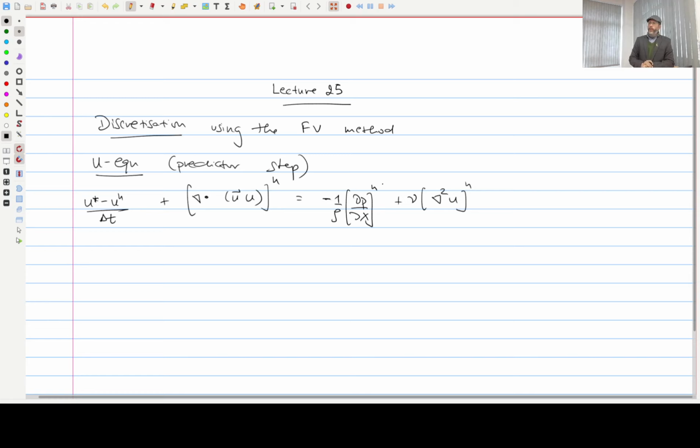When we use the finite volume method, using a conservative form is much more comfortable, because then we can easily integrate it and convert an integral over a volume to an integral over an area. So this is a conservative form of the equation that we had written yesterday.